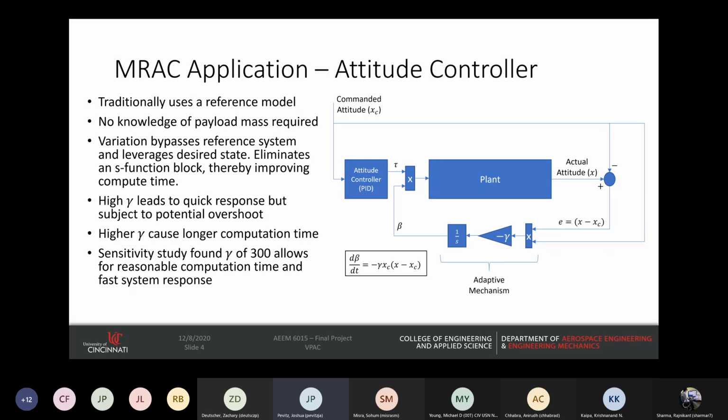It's a little bit beyond the depth to which we went. Are you saying that we could change this gain for each air state? Because we could do that, which we didn't. Okay, yeah, just potentially as something to consider. And in order to do that, you'd have to understand the system stability as you start your controller. So basically, your ability to respond to your initial conditions, however the air vehicle finds itself when I change control laws. Okay. I think I follow. Thank you.